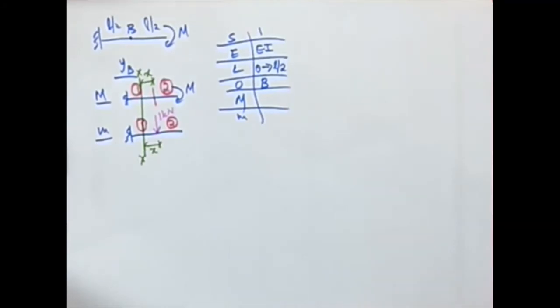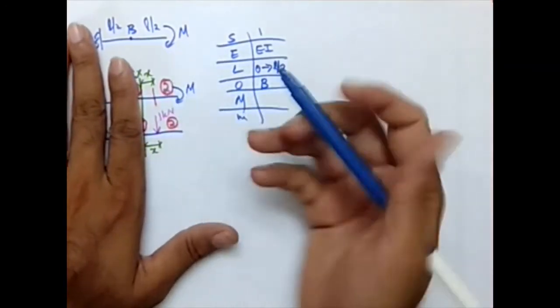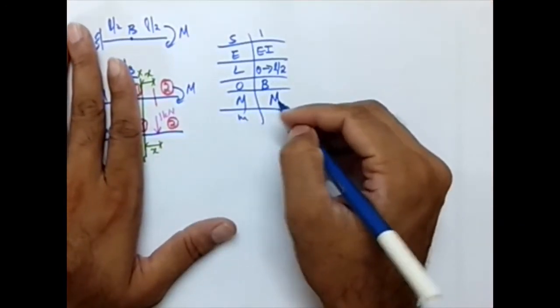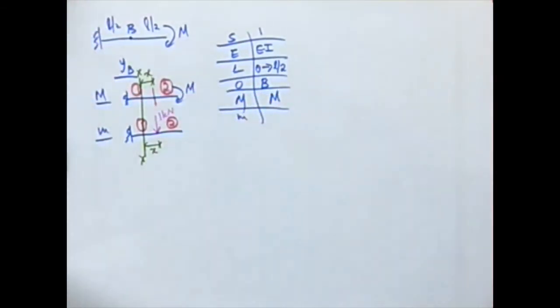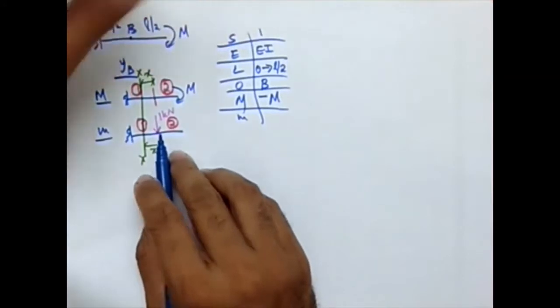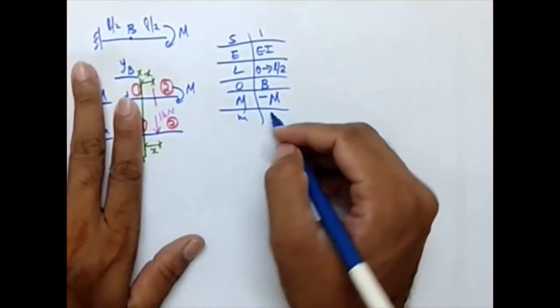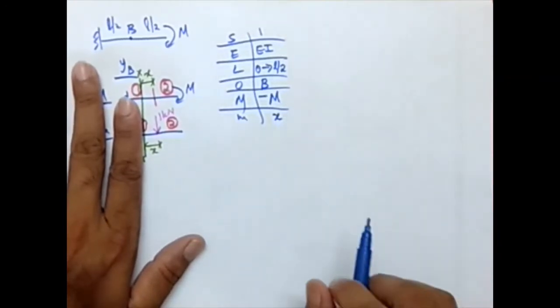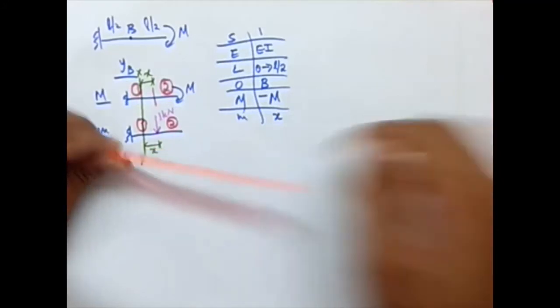Now let's see what the expression for bending moment is. So if I'm taking a section here, what is the bending moment? Capital M. It is a moment, so no lever arm is required. Directly I'll be getting the value M. I need to have the sign convention. So it is hogging, hence it is negative. Now when I'm looking here, the moment is 1 into x. Okay, 1 times x. Sign convention, hogging. So negative.